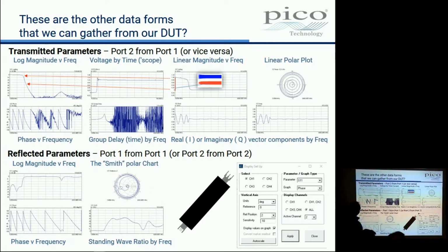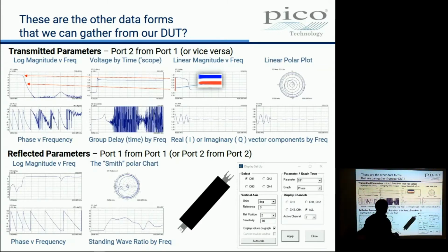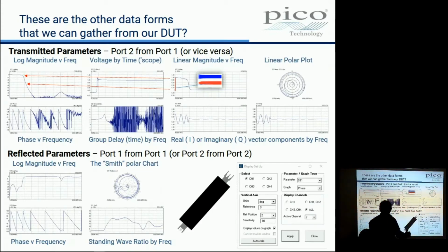So this is a low-pass filter. It is comparatively well matched, low down, and the SWR reading here is 1.2 to 1. And then when it becomes mismatched, that's what we see here in an SWR plot. And this little ding here in the S11 plot is that ding there. So that SWR plot is correct. I just couldn't get my head around it for some reason the other day.